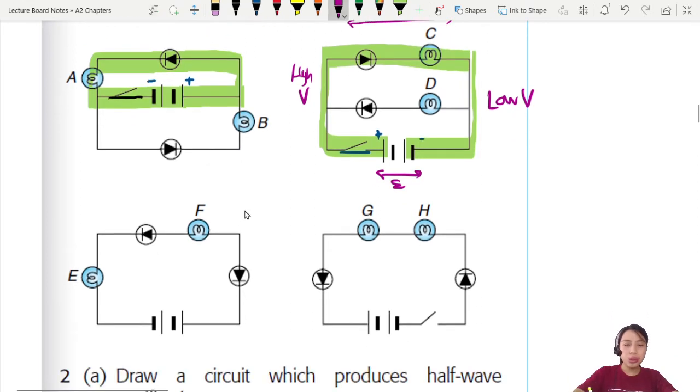Okay, let's look at the other two. Where will current flow? This one is positive to negative. Will current even flow? You see, there's a problem. Current tries to flow this way, but there's this no entry that's opposing. It will not let the current flow. So unfortunately, nothing will light up. The next one. Will this one light up if we close the switch? We have another problem. Current tries to flow, cannot flow. So none of these would light up, which is very unfortunate. Okay, so make sure you know how diodes work because that will be important in this section.